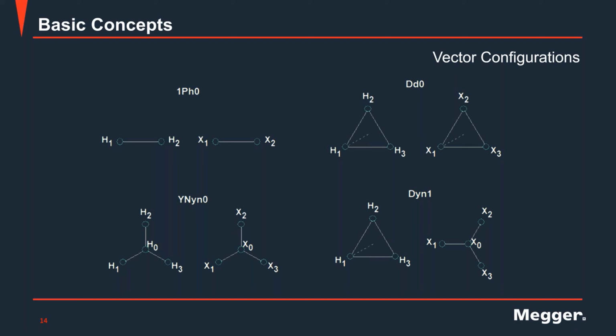The good news is, back in the day, we used to have a table to look for that specific correction factor I need for the transformer I'm testing. But nowadays, either my TTR instrument, or the software in the computer, if I'm using that to control my instrument, will actually do that calculation for me. All I have to do is specify in the software or the unit what is the configuration I'm testing. And again, the software will actually make that correction for me.